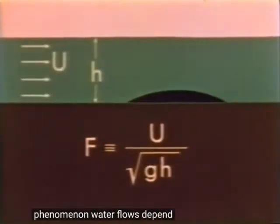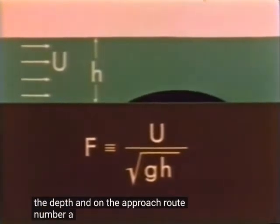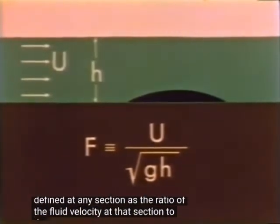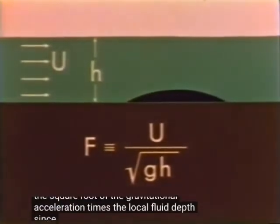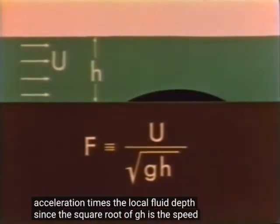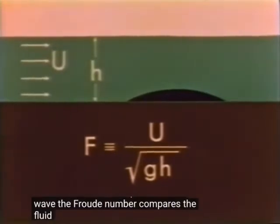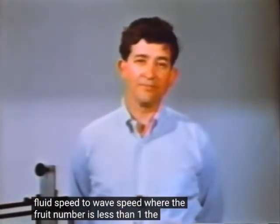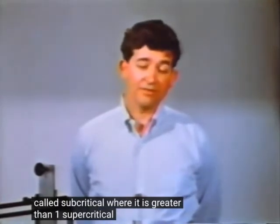Phenomena in water flows depend on the dimensions of the obstacle relative to the depth and on the approach Froude number. A local Froude number may be defined at any section as the ratio of the fluid velocity at that section to the square root of the gravitational acceleration times the local fluid depth. Since the square root of gH is the speed of the fastest small amplitude water wave, the Froude number compares the fluid speed to wave speed. Where the Froude number is less than 1, the flow is called subcritical. Where it is greater than 1, supercritical.